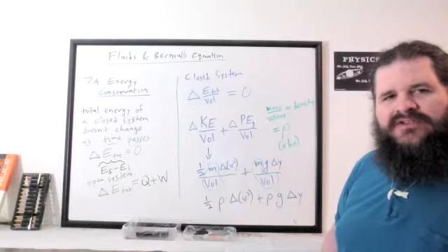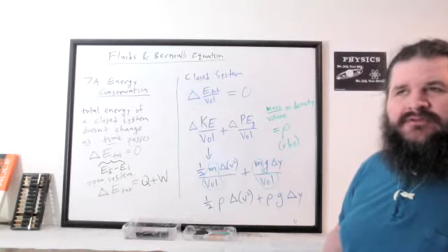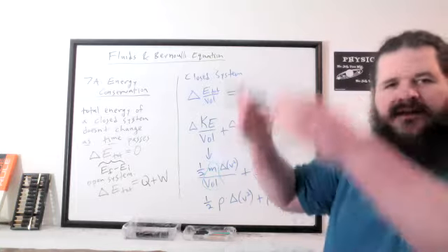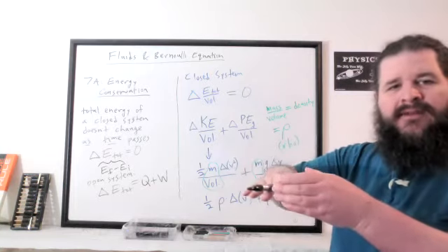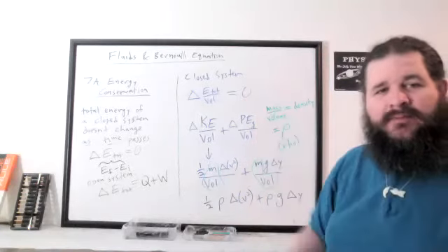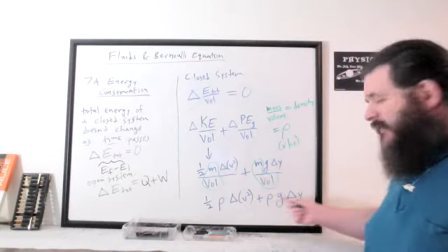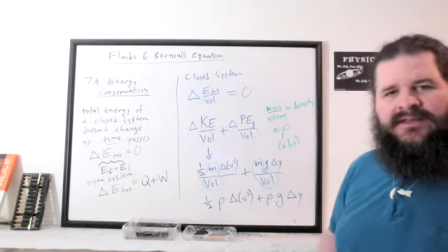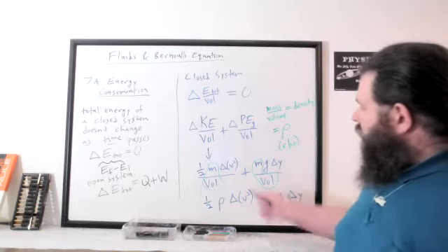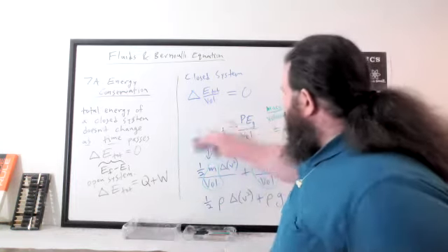And energy density you'll sometimes see referred to as head. And I think this is from fluid flow engineering, like dealing with pipes and stuff. Head represents, if you take a standpipe, like I was drawing earlier, and measure how high the water rises in that standpipe, we refer to that height as the head that the water reaches. So this would be sometimes called the kinetic head and the gravitational head. But that's just another word for energy density. So we can fill those in as our change in kinetic energy density and our change in potential energy density as actual formulas.